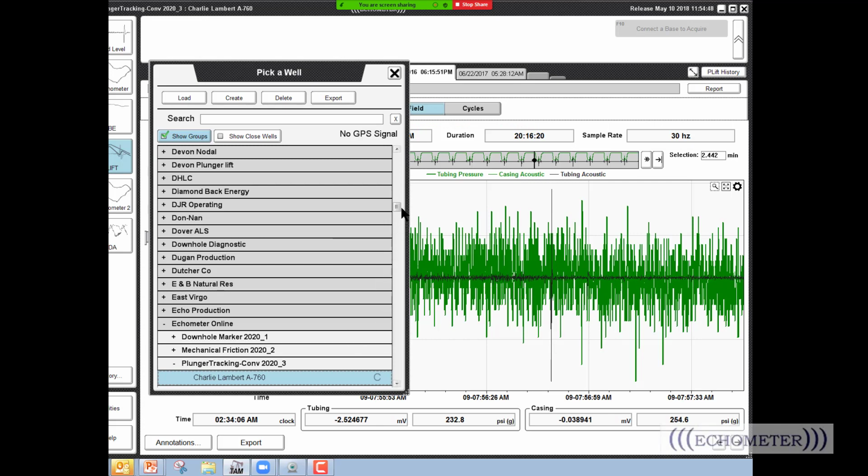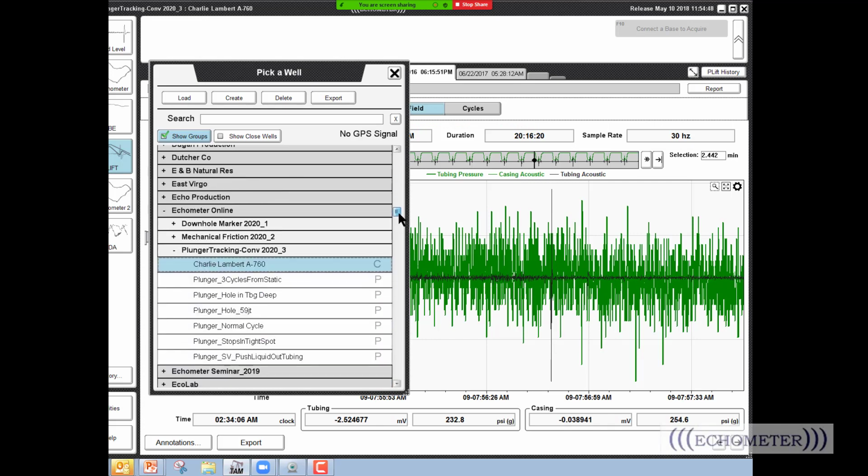One more question is, control valve closed, and line pressure declines. What's the possible cause of it? Well, line pressure declines means the flow is going away from the motor valve down the flow line.